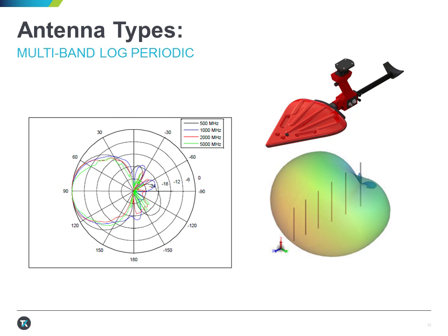The reason why this is important, as we're using this type of antenna for direction finding, is that one must understand that getting a good peak out of the signal actually takes quite a bit of skill. The front to back ratio also must be taken into account. As you start peaking the signal or looking for peak signal amplitude, it's important for the operator to go 180 degrees behind him, in the opposite direction, to determine if the signal is actually coming from the opposite direction. This is due to the fact that we may have a 10, 20, 30 dB front to back ratio, and sometimes you might be pointing in the opposite direction.